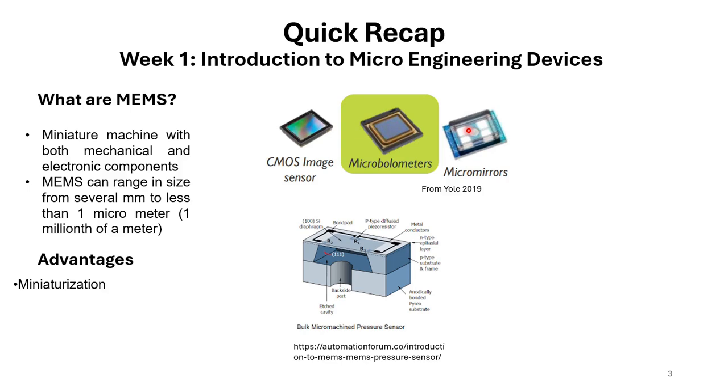Then another advantage is that it has low unit cost. Why do we say that it has low unit cost? MEMS can be fabricated using a batch fabrication process, meaning we can fabricate multiple devices in the same step, because in the same wafer we can have multiple devices and we can fabricate them together. So when we see the cost per unit of the device, like the cost it takes for fabricating one unit of a device, it reduces drastically.